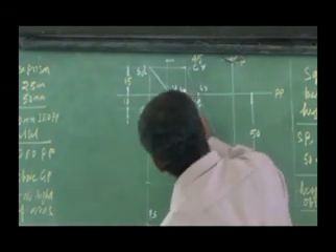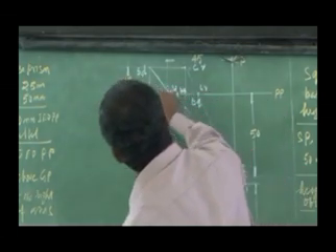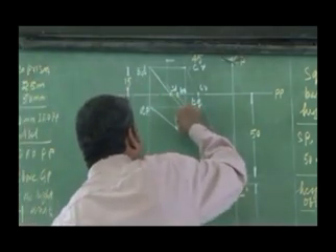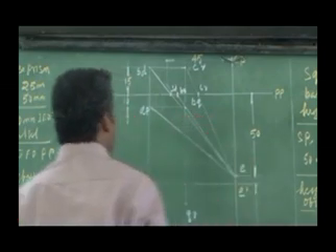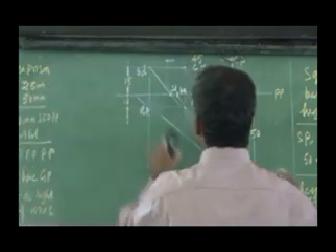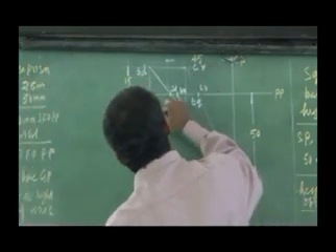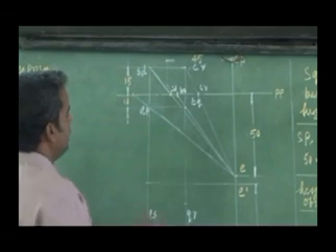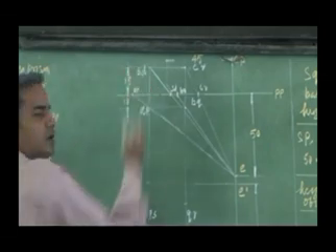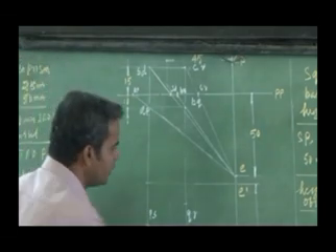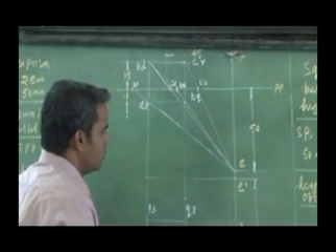Carefully extend. Visual ray properly. In a normal visual ray line, I am not able to get the intercept. So in the same manner, I extend it to get the intercept on the picture plane. Where it intersects here, that is the location of intercept AB. Right, I have got the intercepts here. Now you draw the visual ray lines for your front view.